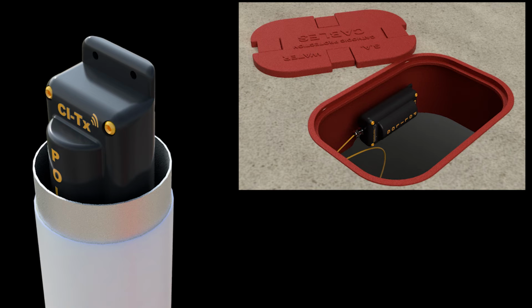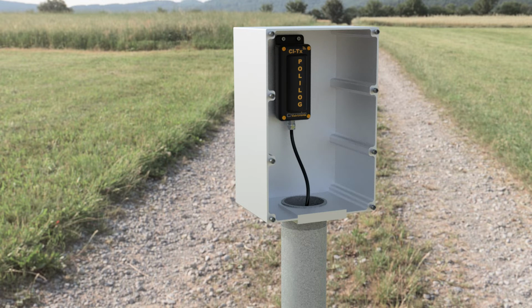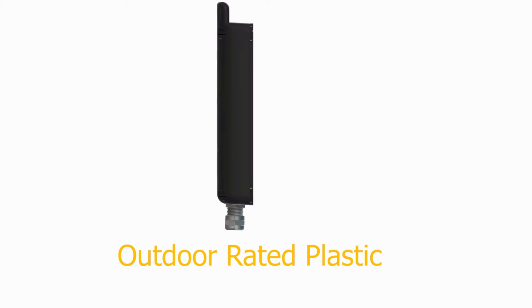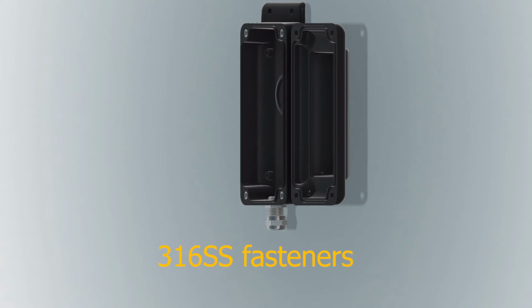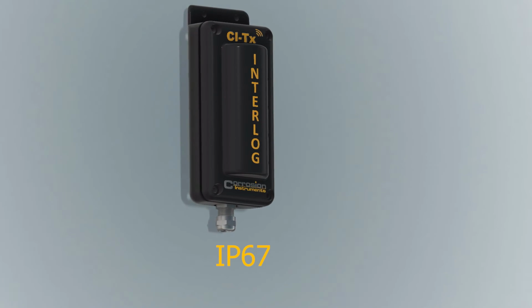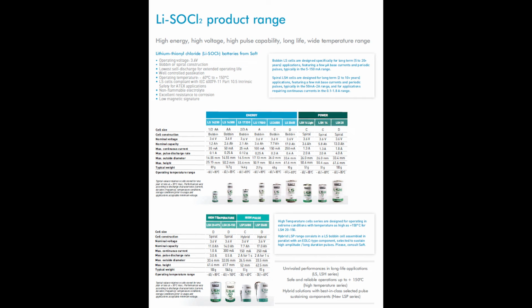Our custom-designed enclosures were designed specifically to fit inside the various types of test points which are commonly used in Australia. They are made from UL F1 outdoor-rated plastic and utilize 316 stainless steel fasteners. The enclosures are IP67 rated, even with the cable gland and external antennas installed. We use a long-life, high-temperature rated lithium thionyl chloride battery and expect the battery life to be in excess of 10 years under typical operating conditions.